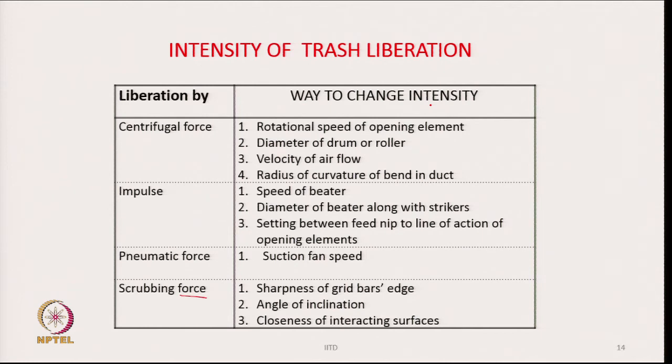So, if we want to increase the force, the rotational speed of the opening element can be raised, the diameter of the drum or the roller can be made larger, the velocity of the airflow can be increased, or the radius of curvature of the bend in the duct can be increased. So, these are the ways by which we will be able to increase the magnitude of centrifugal force.